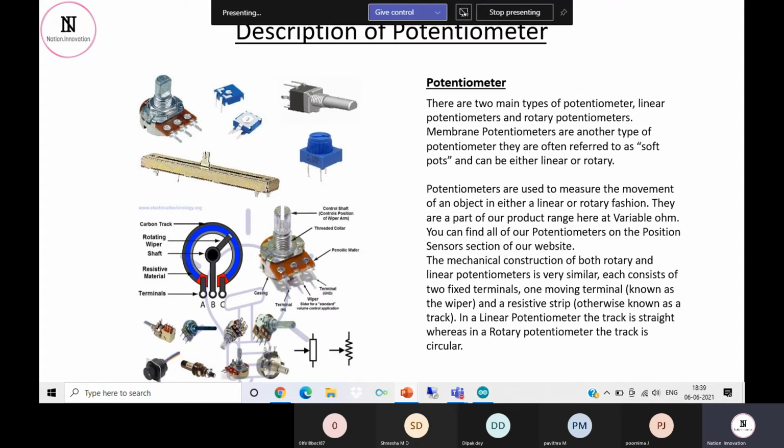And if we swap things out, like if we connect the positive end to this side and the negative end to that side, the value will be different. Fine. So if we connected A to be the positive terminal, then this can be the highest end or this can be the lower end. This is going to give 0 volts as an output, or this is going to give a maximum of 5 volts as an output, and with the swap, the reverse will happen. Fine. And the central pin, pin B, which is the wiper pin, helps us get the exact value, at which position your potentiometer knob is at present.